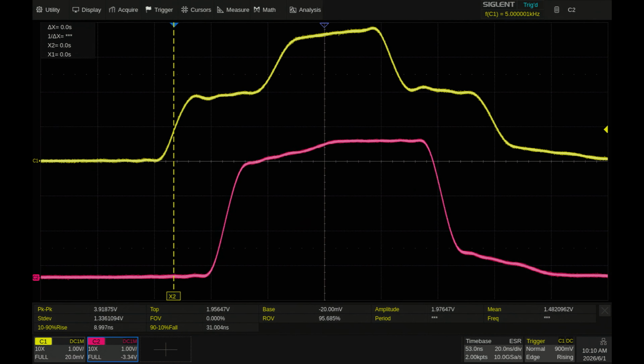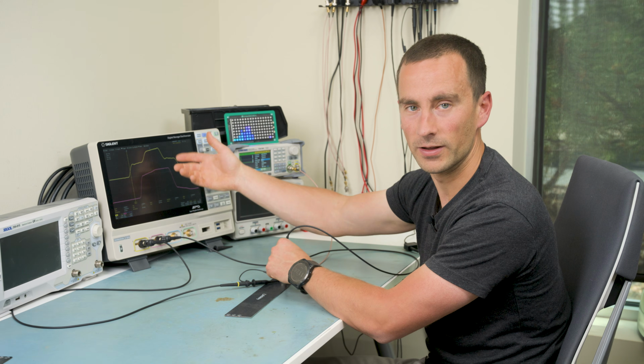And if I make this longer, we'll get that very obvious stair step where we have the pulse we're sending plus the reflection, and then just the reflection. However, at the end, we're only getting the reflection, and it's about 3.5 building up to 4 volts if we let it run long enough.